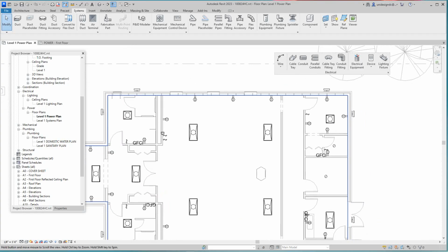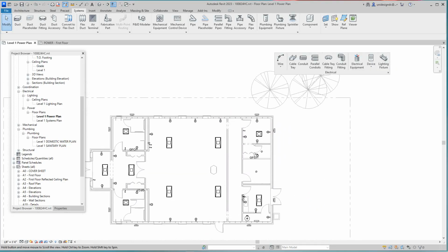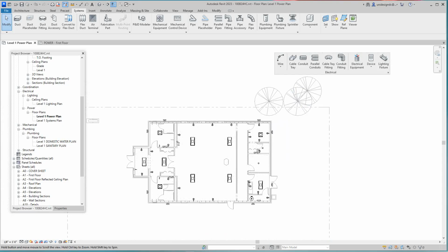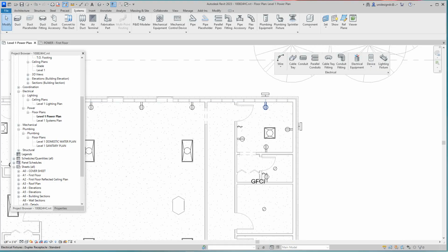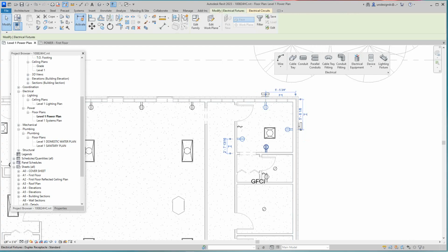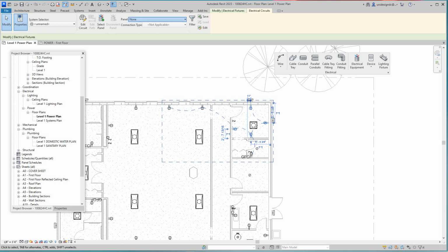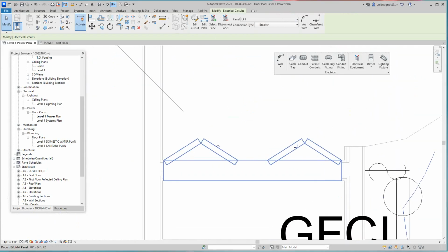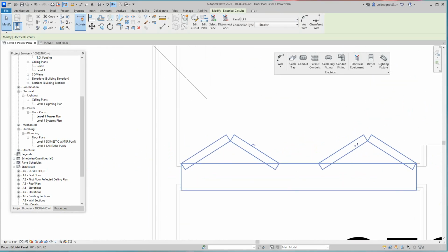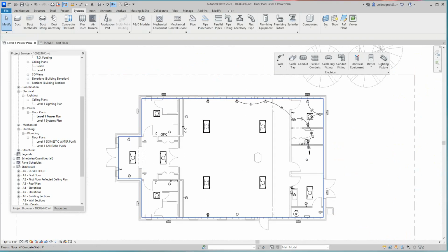And then here we're into our power plan. Now what we do here to wire these up and make a circuit, I did this before, but I'll do it one more time. You want to go here, and let's select these 4 here. And then I want to associate it with my panel, with this LP1. And then here, if I tab this and select this, you can zoom in and pick the type of wire arc we want. I want to select that one. And there it is.